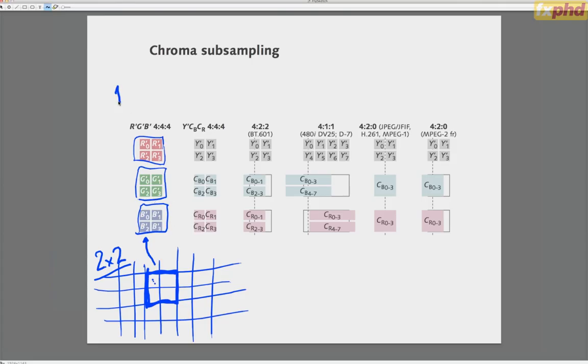So what we're going to do is we're going to take this 12 bytes of RGB. Just for the sake of argument, we'll say for the moment these are 8-bit components. And first, we're going to transform them through a matrix into Luma and 2 chroma components. The Luma I've shown gray, because we kind of associate lightness with gray. And this is a little bluish, it's the CB component. This is a little reddish, it's the CR component. And so far, we've still got 12 bytes of information. But we've set ourselves up here to be able to discard chroma information, because all of the lightness is in one component.